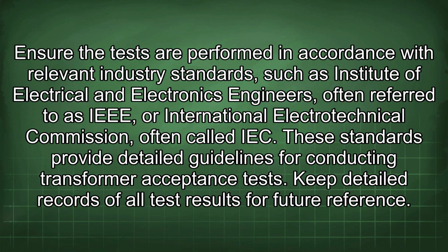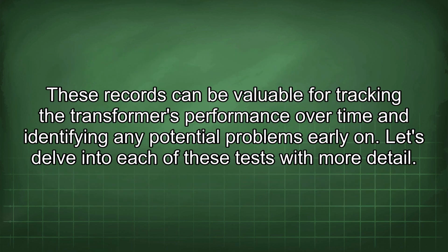Ensure the tests are performed in accordance with relevant industry standards such as the Institute of Electrical and Electronics Engineers, often referred to as IEEE, or the International Electrotechnical Commission, often called IEC. These standards provide detailed guidelines for conducting transformer acceptance tests. Keep detailed records of all test results for future reference. These records can be valuable for tracking the transformer's performance over time and identifying any potential problems early on.